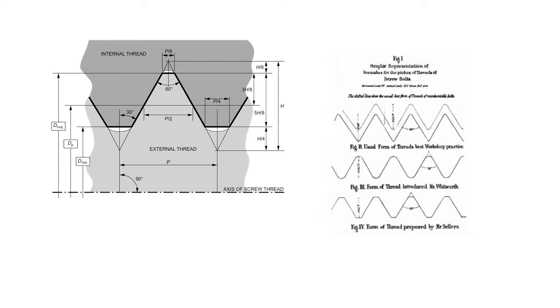We've come a long way to agree upon what standards to be using. Most parts of the world use ISO standards, while US and Canada use UNS. And in each system, there are both fine and coarse threads. Nevertheless, the 60-degree thread angle remains the same across all systems, as well as the relation between major diameter, pitch diameter, minor diameter, and pitch distance.